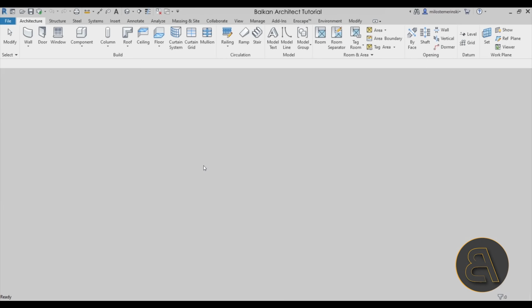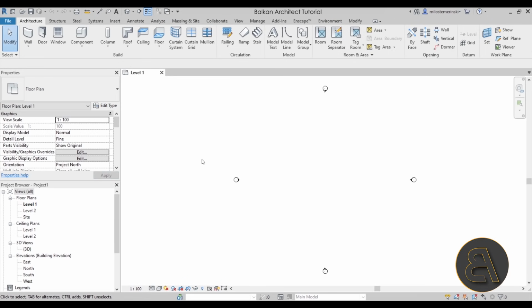Now I'm just going to click OK to get Revit started. And as soon as Revit opens up, let's explore the first approach to creating facades or metal panel facades in Revit, or generally any other type of panel facades. So the first and easiest way to do this is the manual way. It is going to give you a lot of versatility, but it is also going to be the longest one to create the actual facade.